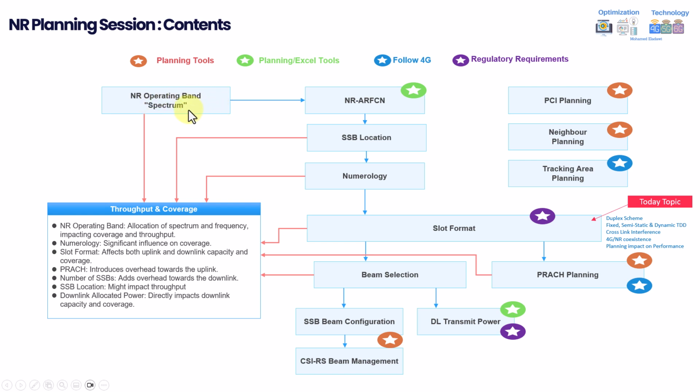We'll also go through how to verify or check the existing bandwidth or spectrum from the UE logs. Then we'll go through how to configure, and the theoretical understanding of, the SSB center frequency or the channel bandwidth center frequency and so on. Then we'll give very good and interesting inputs about the SSB location. Whenever you configure the SSB location, you need to understand what kind of impact it has on performance, even throughput or coverage or all other aspects. So this one will be covered in detail.